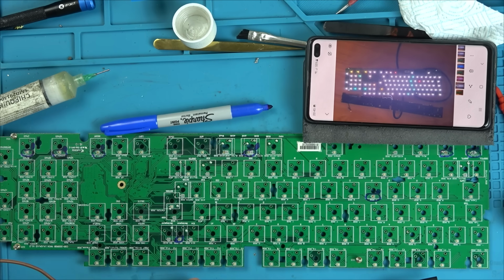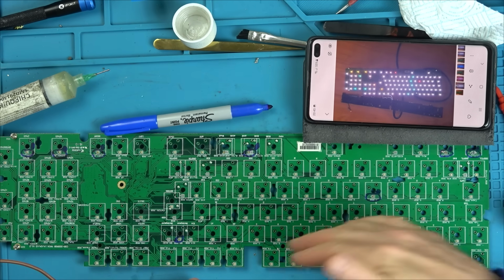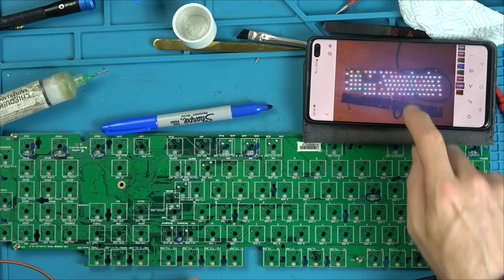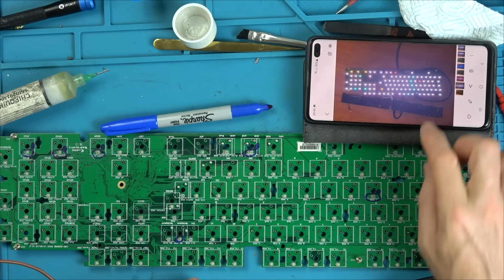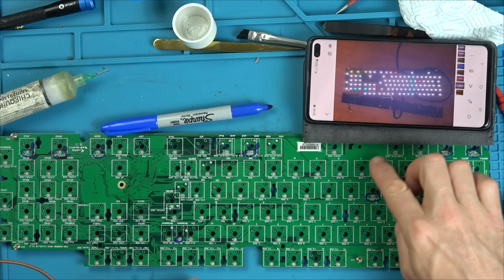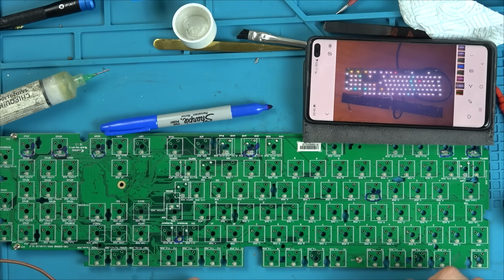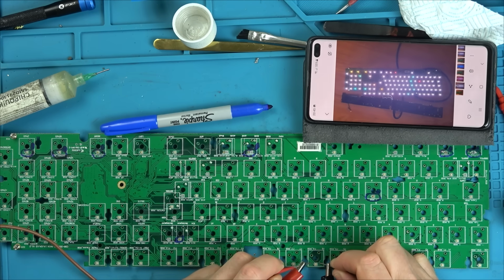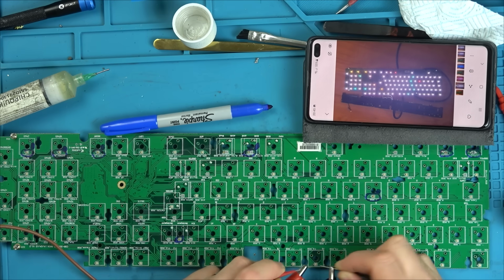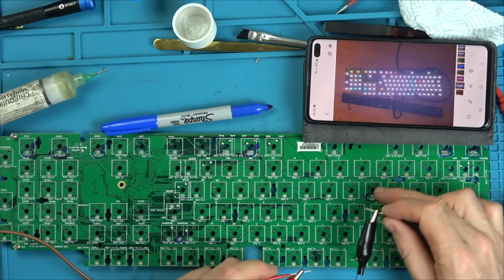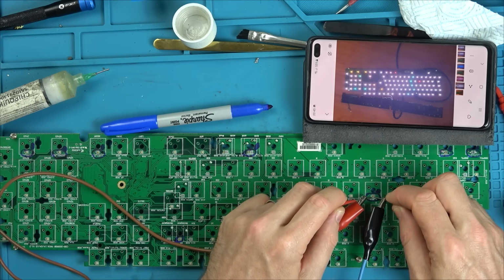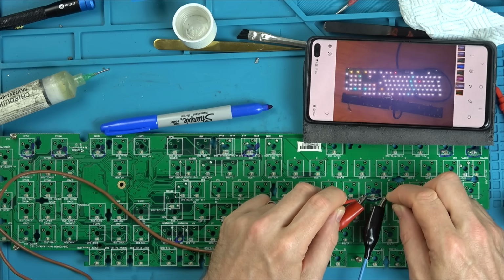So I think because there's faulty ones in circuit on the matrix, however it works, I reckon it's throwing the cyan ones out, and when we replace the others, they will get the correct reading. For example, if I go across this cyan one up here, check it out. If I go across the bottom, it will be green, and you can see it's lighting up green, red, and blue. Yeah, I'm only holding on for a second. But now, if we go across this one, which is red, you can see that we've got no blue, we do have red, and we've got no green.